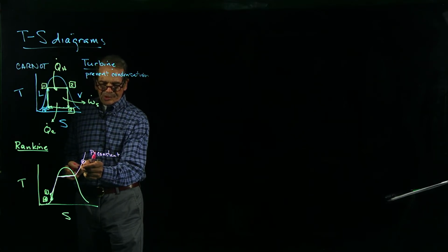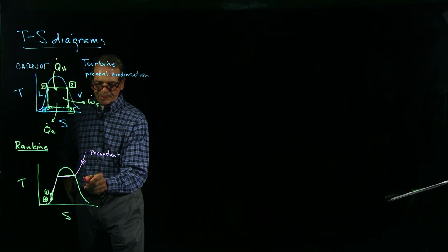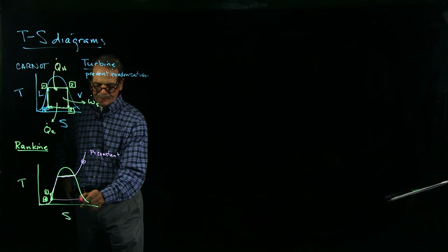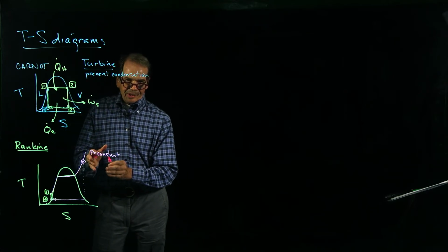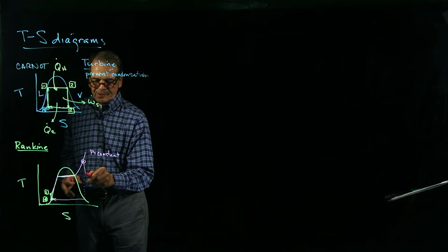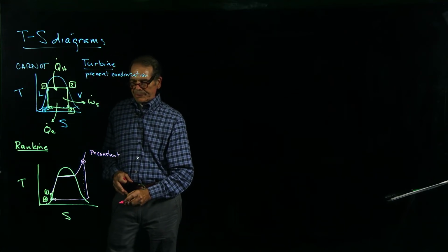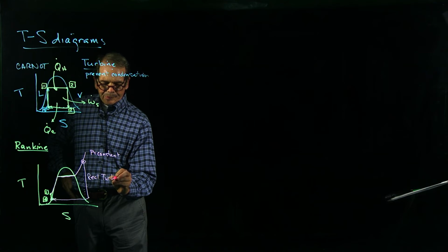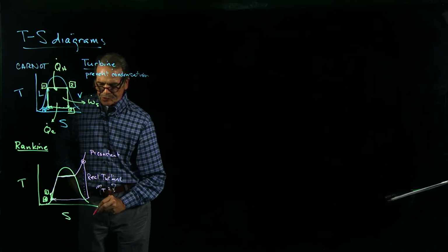When I put it through the turbine, I don't want to condense it. This is going to be an isentropic turbine. The ideal would be something like this, going down to there, meaning this isotherm, where I'm removing heat. We know that the turbine is not going to be isentropic, and so the actual curve is going to look something like this. Maybe. So this is going to be a real turbine, with some efficiency. Don't know what that is.